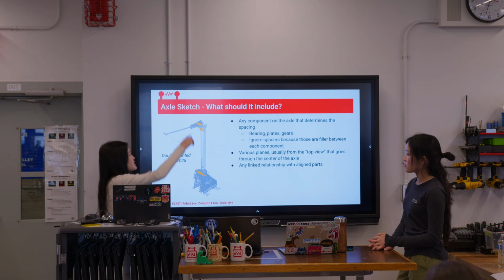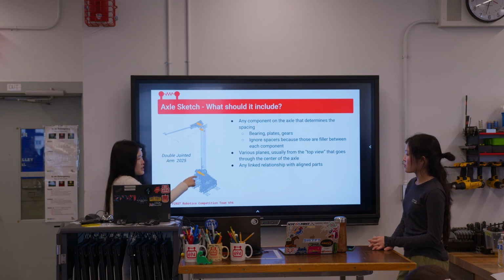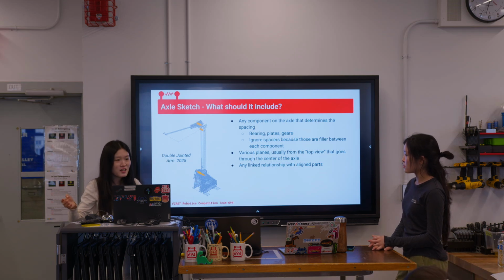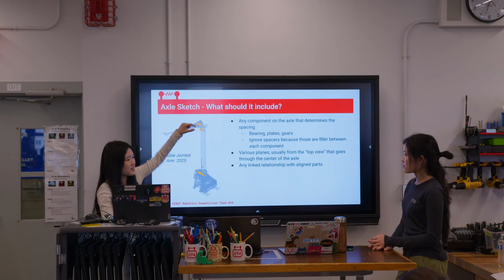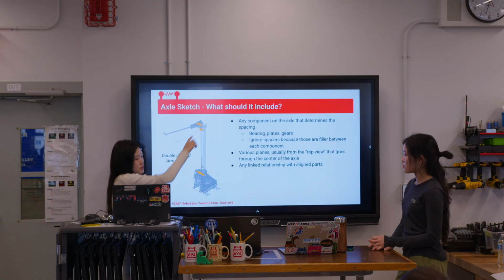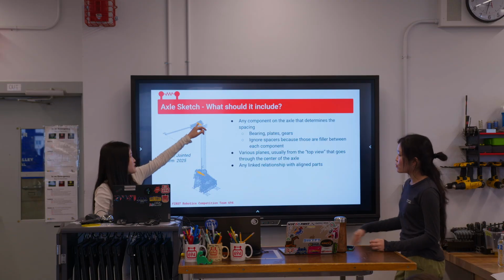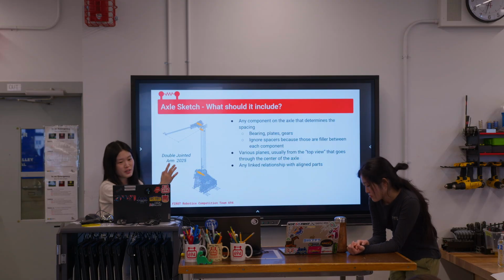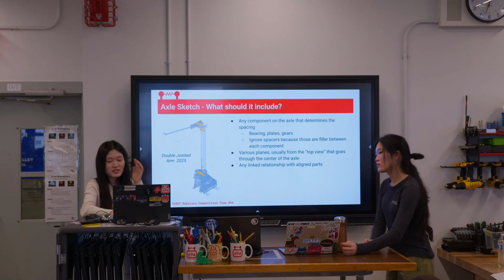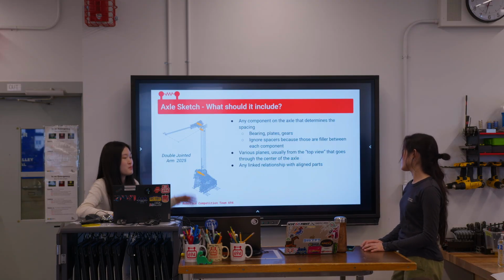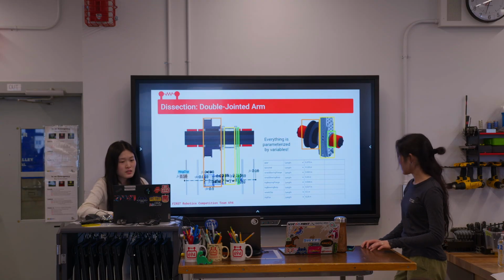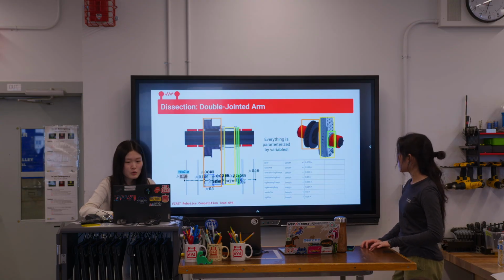And then when I make the second joint, I'll look down at the first joint and use the coincident tool to physically click the center of the pulley on the second joint and the first joint, and physically make it line up on the sketch. So there will never be a case where it will not line up if you do this on your sketch. This is just another example of how it relates.